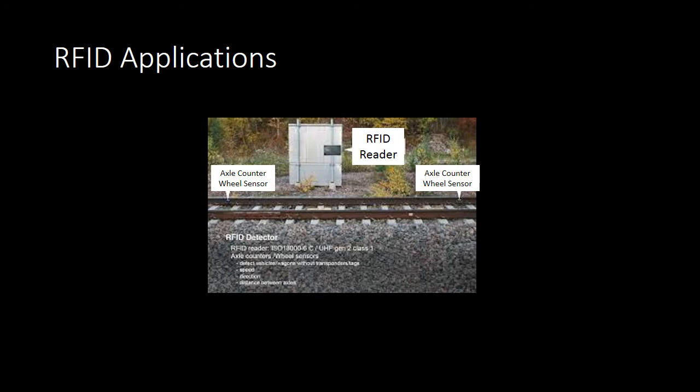Rail movements can be monitored easily by installing a single RFID reader to scan tags attached to rail wagons. These tags can contain the company information, load composition and source and destination of each wagon. When one reader is used, tags need to be attached to both sides of the wagon. Two axle counters, located 3 meters apart on the tracks, will detect wagons without tags and speed, direction and distance between the axles.